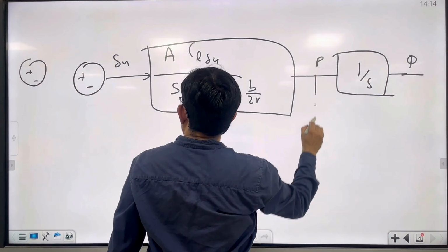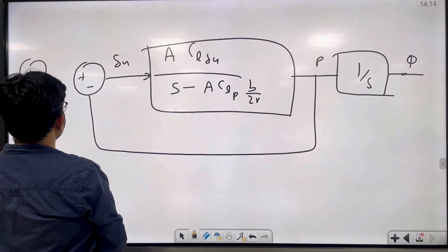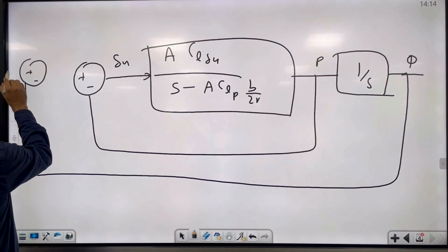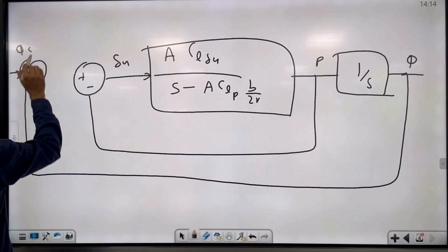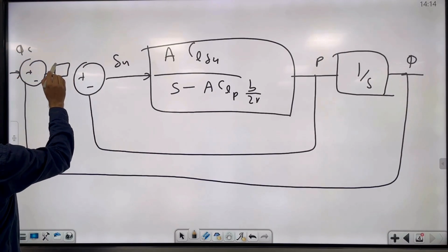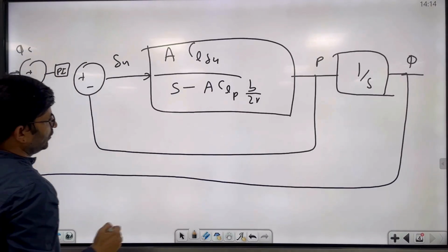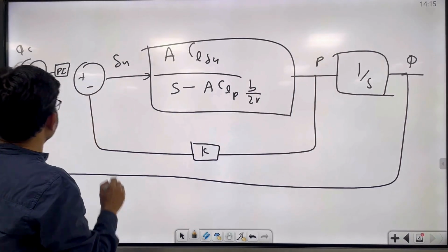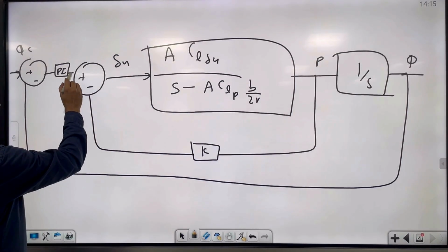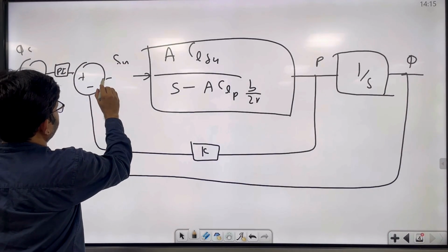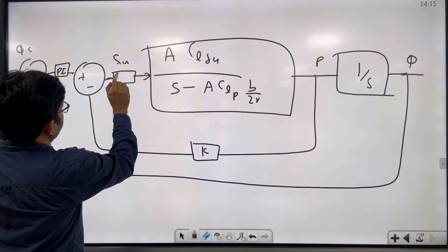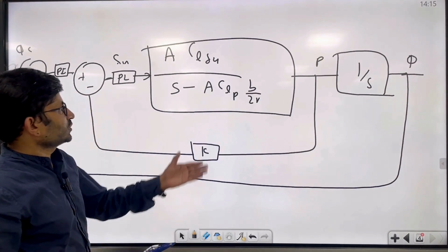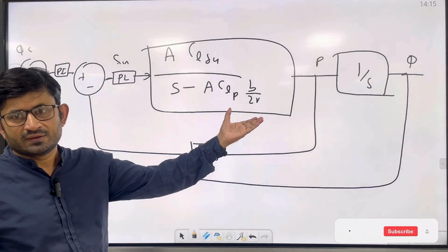Here you can take a feedback and multiply, and here you can take a feedback, that will be phi command, and here you can use a PI controller. Okay, and here you take a feedback, some gain K value. And before supplying to the delta A, you will put the physical limit, rate, position and actuator dynamics. So this is clear, right? How simply we have drawn.